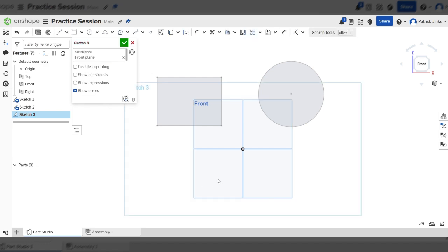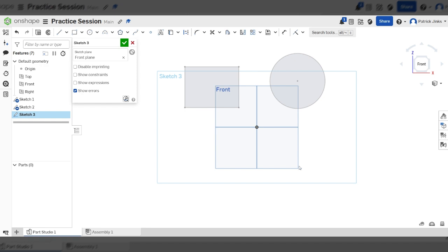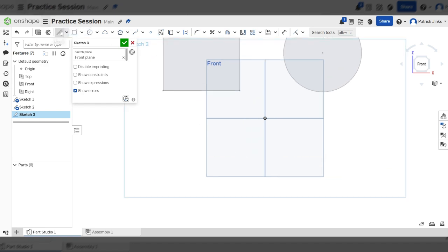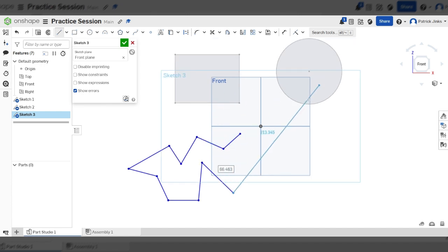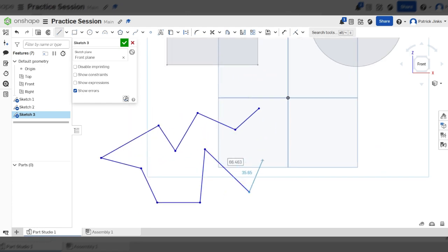Click the sketch, click the front plane, and what I'm going to do now is something a little bit more complicated, that's a bit more fun. I'm going to click the line tool, which is actually the first one of the sketch tools that you will encounter on the toolbar. How this works is every click it just draws a new line off it. So in this bottom corner, you can make a zigzag, a lightning, a Christmas tree. You can make whatever rough basic shape you like. Mine isn't really anything at the minute. But what is important for this that you don't need to consider with the rectangle and the circle is that this is not already a closed shape. This means it is not going to go grey inside until I join the points up.